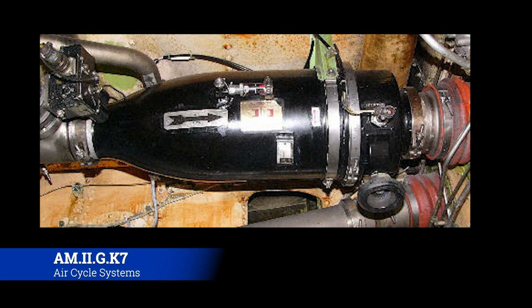Okay, another component that's essential to the success of the air cycle system is the water separator. Effectively, cool air from the air cycle machine can no longer hold the quantity of water it should whenever it warms. So it basically squeezes, because all those molecules are coming together so tight that it starts to squeeze whatever water is being held by the air out. So a water separator is used to remove the water from the saturated air before it's sent to the aircraft cabin. If not, you get all kinds of crazy fog and all kinds of problems.